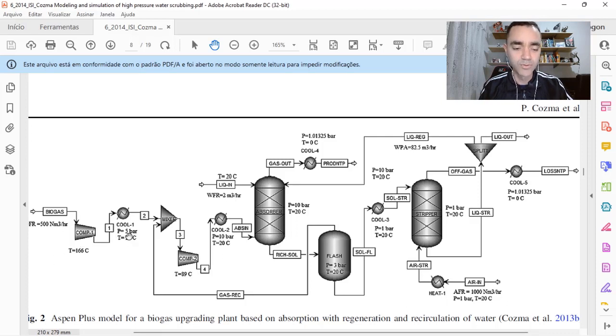Because if I have 3 bar here, in terms of heat and material balance, it makes sense to mix a 3 bar fluid or recycle stream with a 3 bar discharge stream, and with that have the suction of my second stage of compression. So this is the first improvement that I have seen from this process flow diagram.